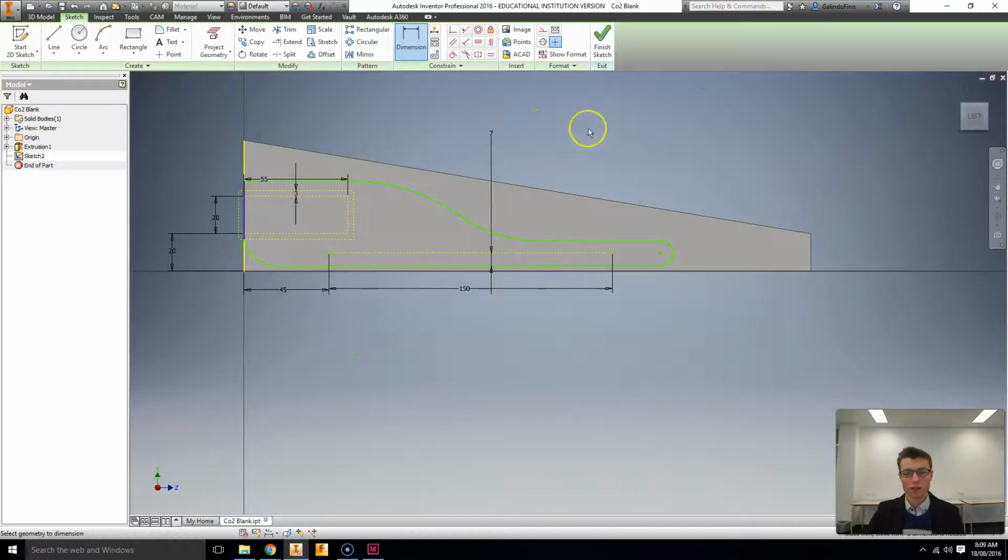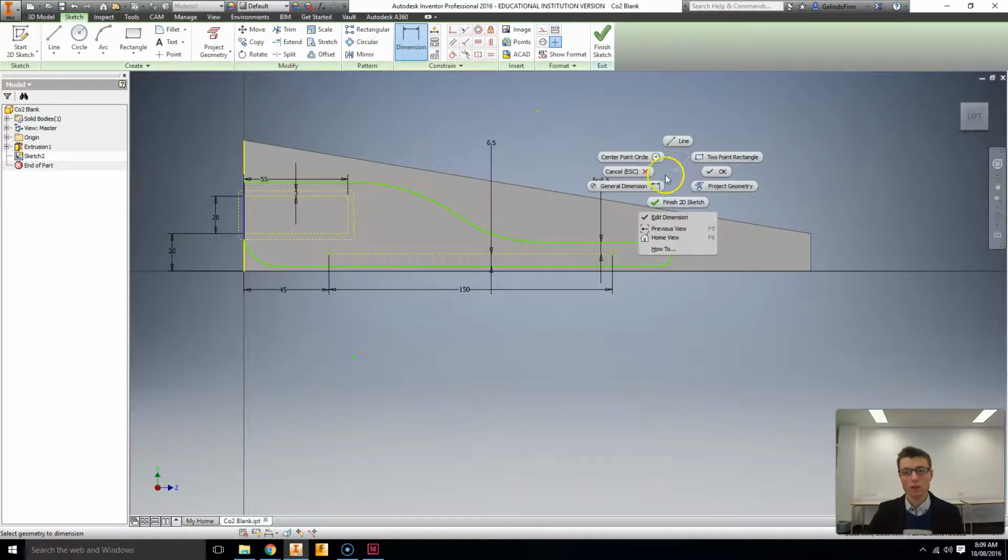Okay. Now I like making things really even, so I'm going to select the line again and do this top line here and make this equal the same as the 7. So while it's highlighted like so, I'm just going to click it and it automatically uses a function to match. If I change this now, say to 6.5, you'll notice that that changed to 6.5 as well. I also want to move this point to this point on my axle hole, so that it's perfectly at the end.